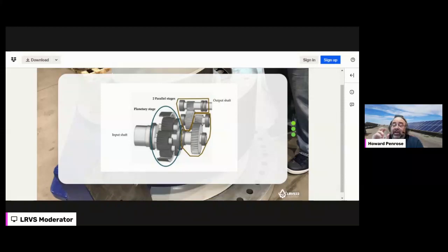So I have my pinion up at the top. That's going to be my high speed. That's going to be 1,200 or 1,800 RPM. A majority of the towers are 1,200, but there's plenty that are 1,800 RPM. Then there's a central one, and then what they call the hollow shaft gear. So that's my 3 stages. And then you have planetary.